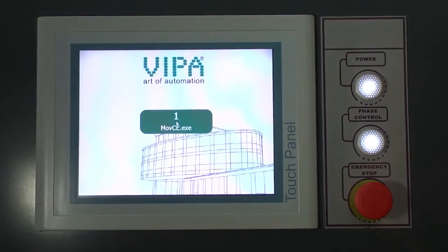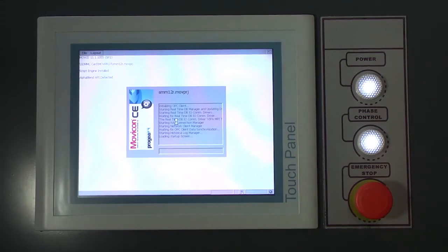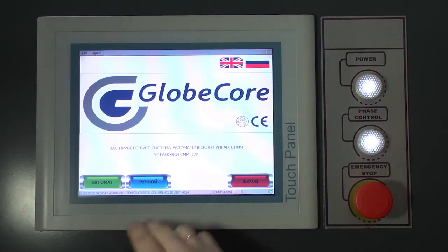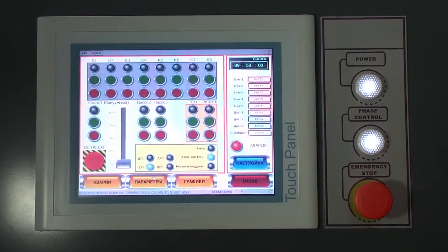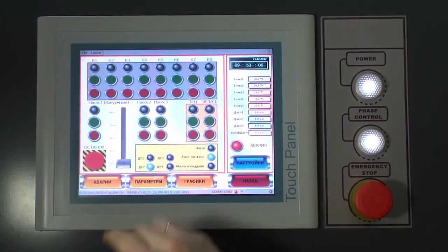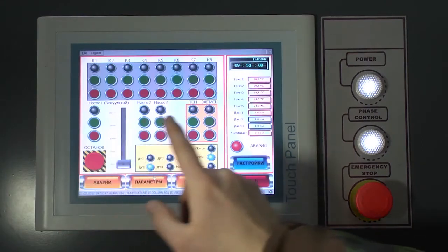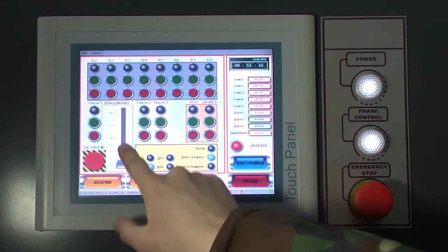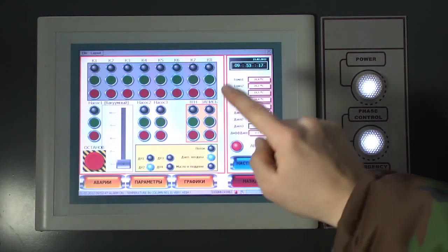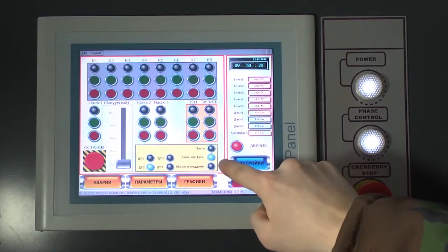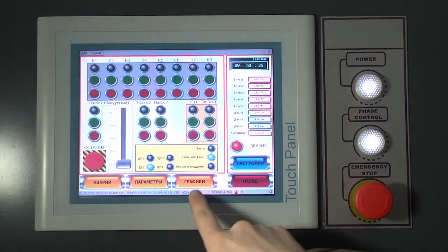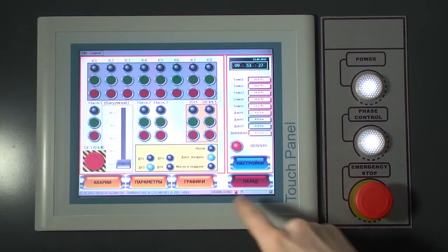The system is controlled from the control panel. It features manual and automatic operation modes. The manual mode makes all valves, pumps, and the vacuum pump accessible for direct control. Pump rotation speed is controlled with a slider. The panel displays oil flow, air pressure, presence of oil in the base, emergency shutoff, graphs, parameters, and malfunctions.